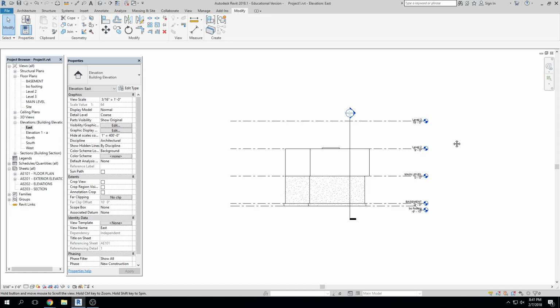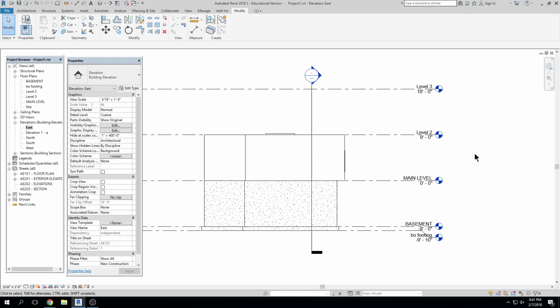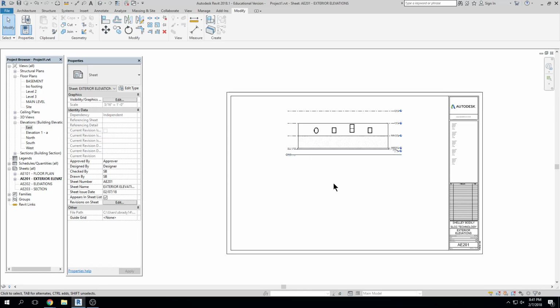We'll just leave it. What happens if you bring two drawings onto the same sheet that have different scales? It's okay. It doesn't matter. Yeah. That is one nice thing about Revit. The idea of a layout on a sheet is that you can have multiple things with different scales and it works just fine. What really drives the scale is the drawing itself, right? So if all the drawings have different scales, they're fine. They're all separate. They're not one piece, right?